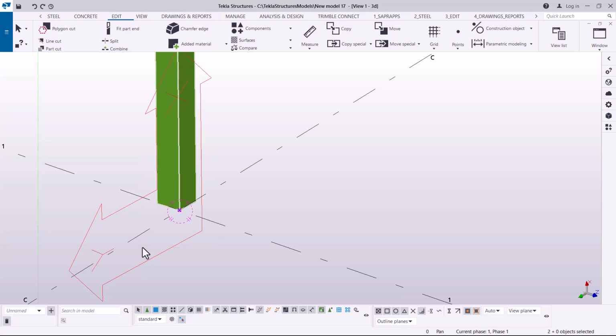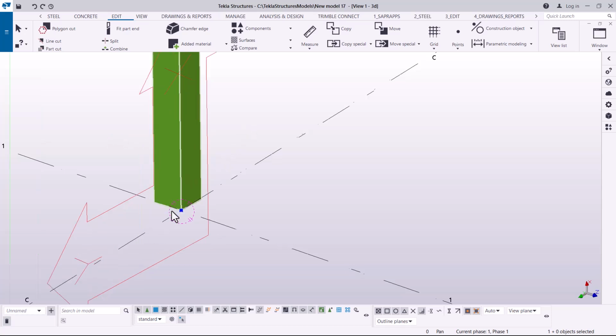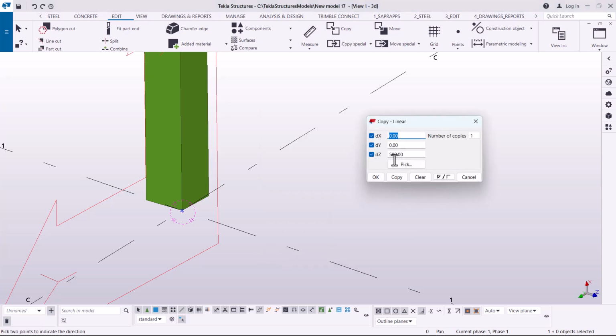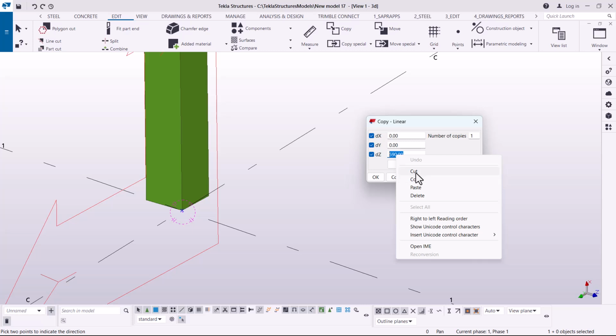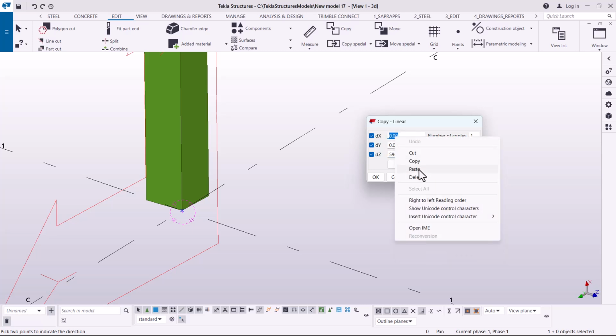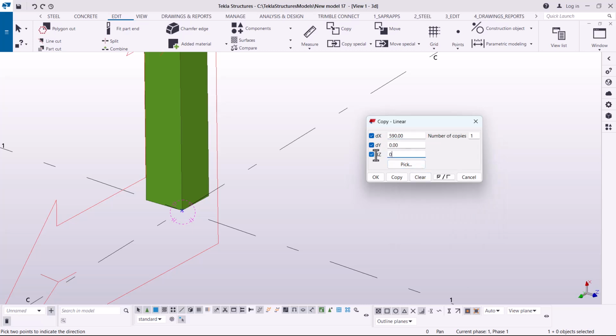So I'm going back to select it, press Ctrl, deselect that part, right click and come to spatial copy and pick on linear. So I placed that on the z-axis, which was not our intended point. I'm going to copy it and place it on the x-axis, and I'll place it right there. Paste, click copy. So once that has been copied,